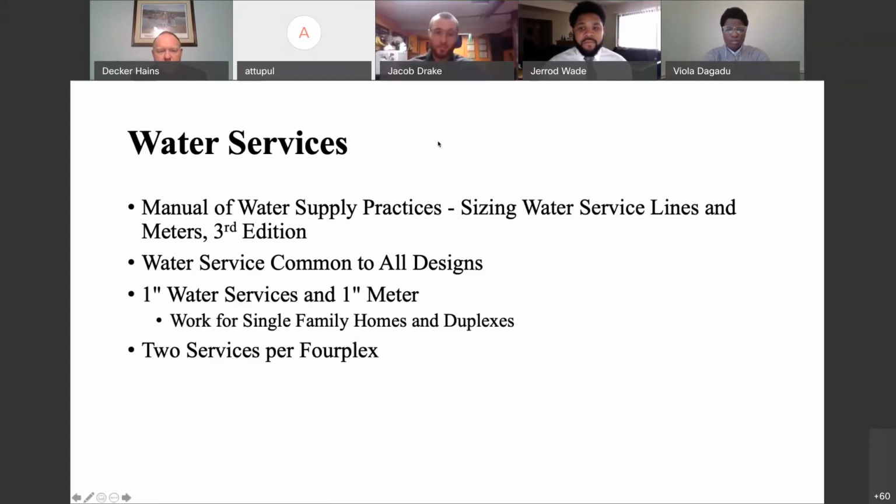Thank you, Gerard. For the water service design for this project, we consulted the Manual of Water Supply Practices, Sizing Water Service Lines, 3rd edition. Since our routing and layout is the same for all 3 designs, the water services are also in common for all of our designs. BWL requires that a minimum 1-inch water service and meter is used in any development in their system. So we started with that as our base for discerning water services.